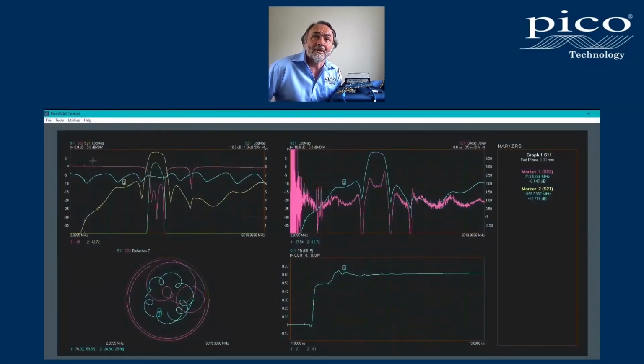Or, moving focus to the 4 S parameters in display channel 1, top left, we could take a look at S11 pink and S21 yellow measurements. A total of 8 markers per channel are available with reference and delta capability as required.